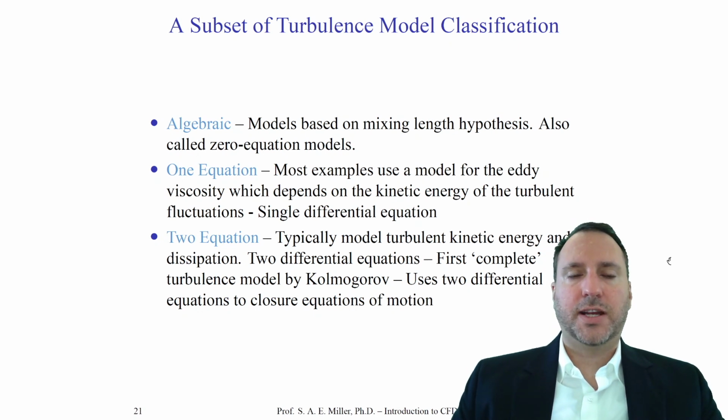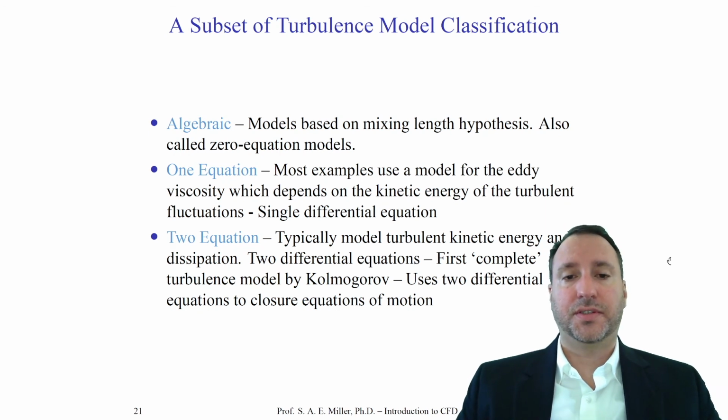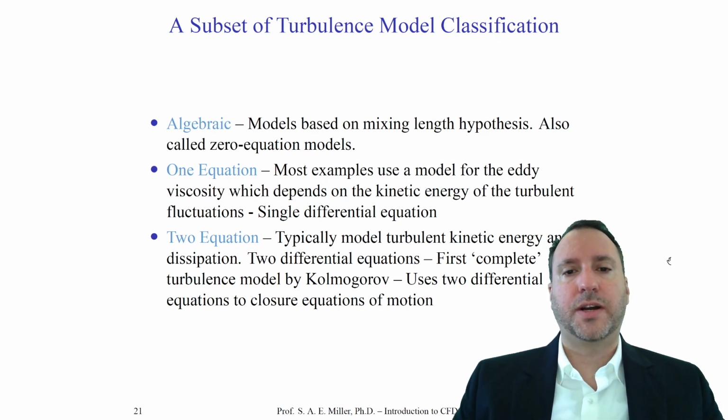Another classification is the so-called one equation models. Now, most one equation models use one particular differential equation in addition to the set of Navier-Stokes equations, which are modified. Most one equation models use what we call an eddy viscosity. An eddy viscosity is a modification of the traditional viscosity term. One equation models are very prevalent in computational fluid dynamics today.